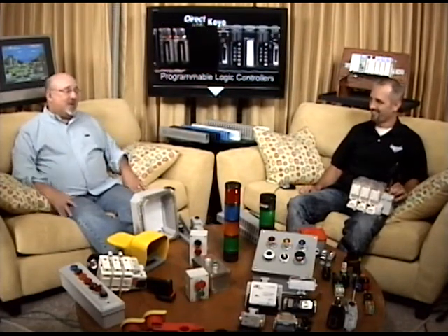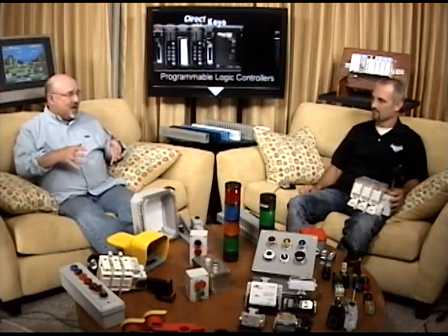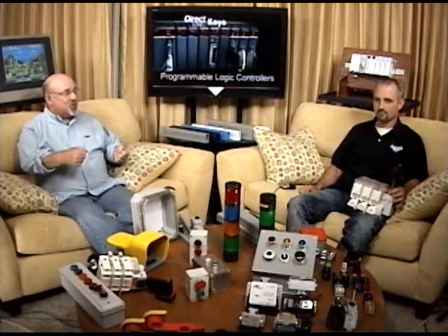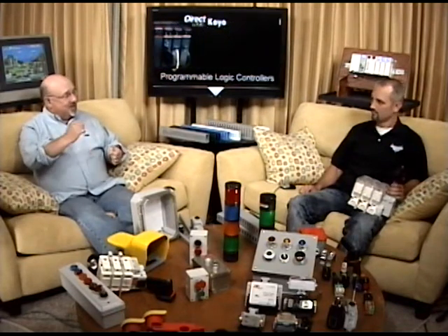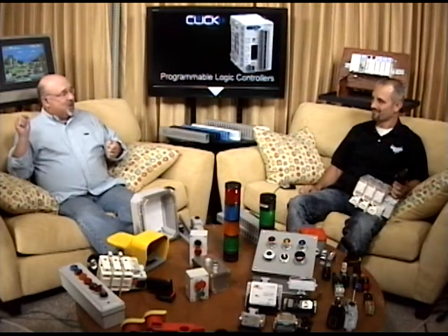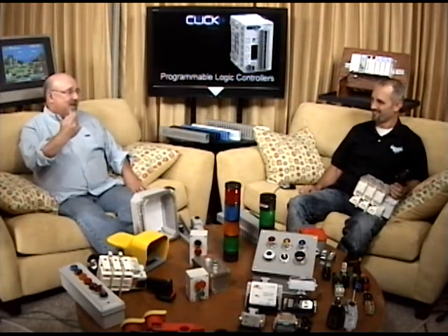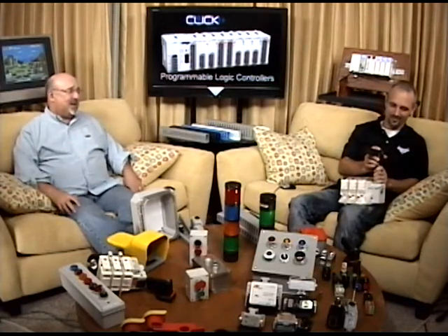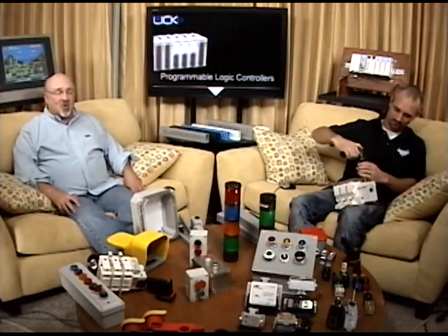The idea was you laid out your panel, mounted everything, wired it, then set the panel inside the enclosure and put the shaft into the operating mechanism. We would literally take the door and slam it shut. If you look at these operator handles, they have a little sharp point on it, so we'd get an indentation in the door that allowed us to put a template on there and drill our holes.